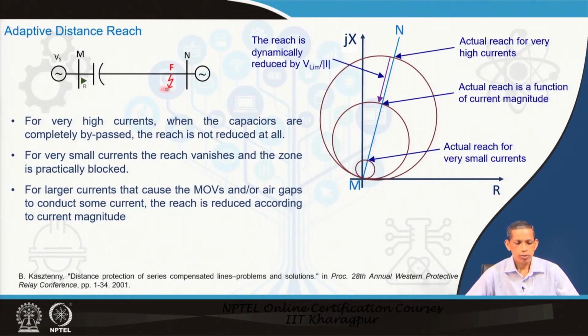So, for this transmission system, with the relay here and the capacitor here, if you see this perspective, we have the larger one, the normal one, for the line 80% let us say, normal line impedance considerations and normal relay setting for that one. Now, with consideration of the lower current when minus of j x c is there in the fault loop, and now in between from this point to this point we are changing the setting using the currents as seen by the relay for that fault.